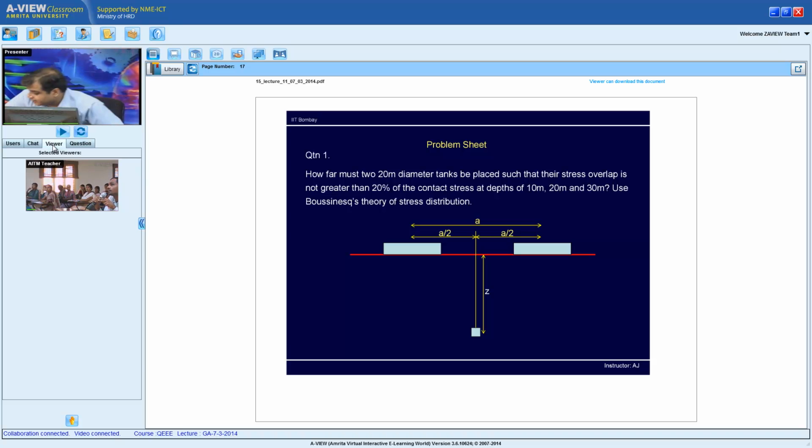Okay, I have not plotted this with depth, but I would still not be wrong to suggest that if you look at the Boussinesq stress distribution for a point load and the load on a footing, and the pressure bulbs which were computed, you would not be wrong to look at the distribution using the pressure bulb. So I would say it's still distributed. It will still decrease with depth. Okay, sir. Okay, thank you.